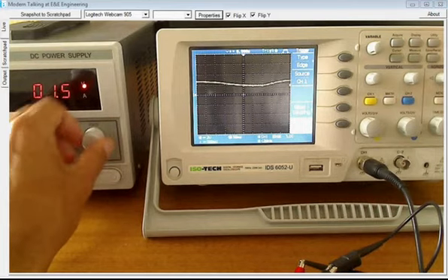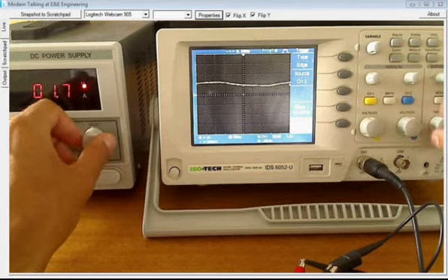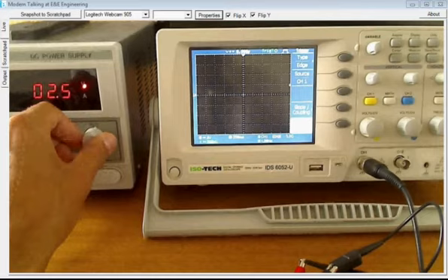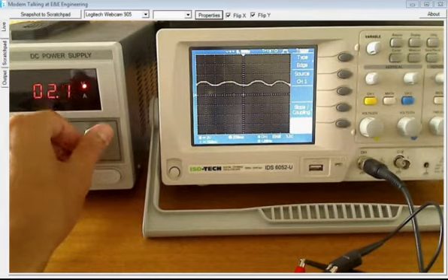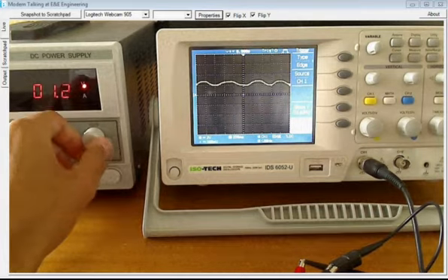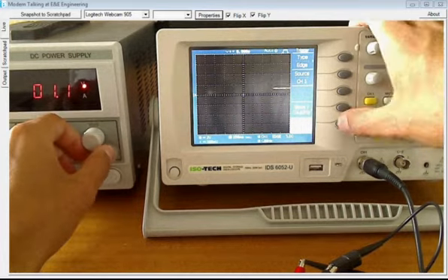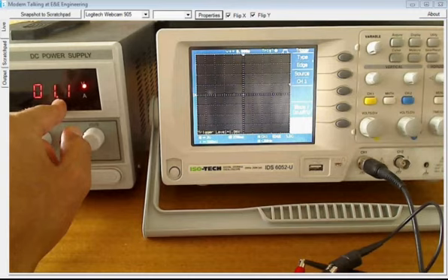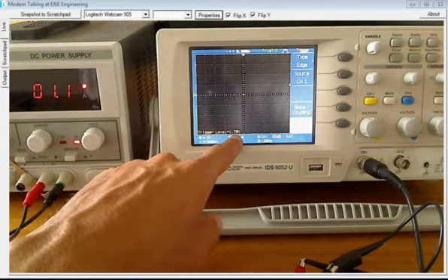So I'm just going to maneuver around there, and I'm just going to zoom out a bit again. So I'm going to turn this to go through 1.7 a few times, and you can see, there we go, it's triggered. If I want to trigger one single time, I'm just going to make it normal. So I'm at 1.2, I'm expecting my trigger to happen at 1.7.